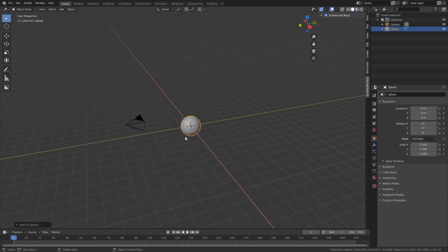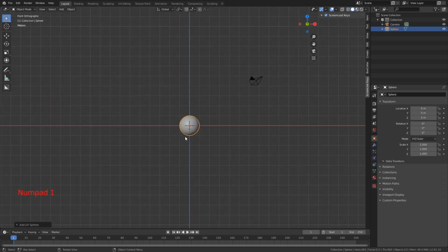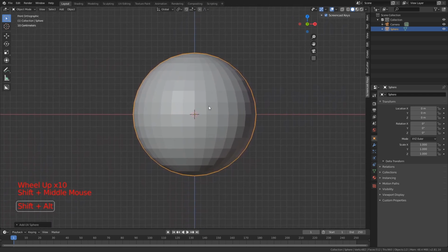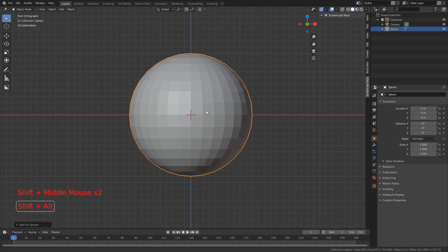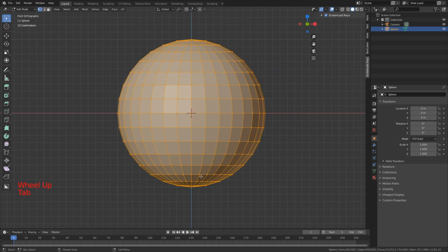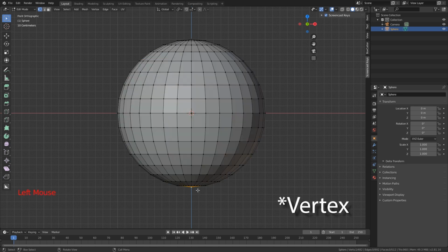That's going to be the base of our balloon. So press 1. And we'll just scroll in, pan with Shift and middle mouse button, and we'll press Tab to go into edit mode. Vertex select is already selected, so just hit the bottom face here. Click this round thingy at the top here called proportional editing.